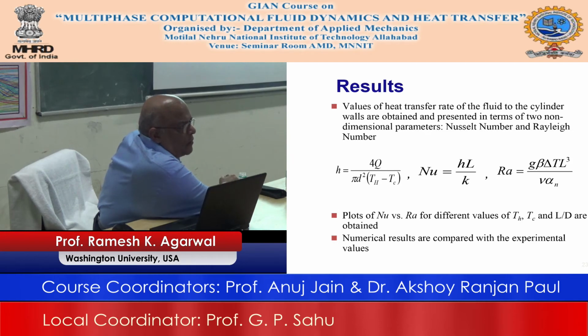K is a very important parameter because this is what the nanofluid is all about. And the Rayleigh number is of course like a Grashof number, and then again you have this coefficient of heat transmission or whatever is the Boussinesq coefficient, temperature difference, kinematic viscosity, and diffusivity.